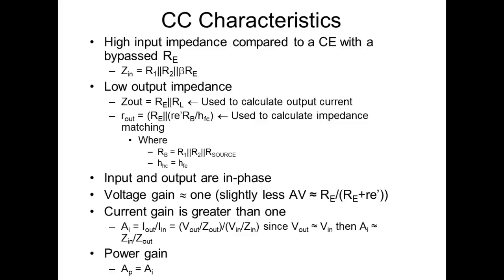And if you go through a resistor, and even if it's base current, if you push a current through a resistor, you're going to get a what? V is equal to I times R. So that means the input and the output voltage cannot be exactly the same, but the only difference between the input and the output is how much voltage is dropped by RE prime. So for all practical purposes, we're going to say this thing is equal to approximately 1.